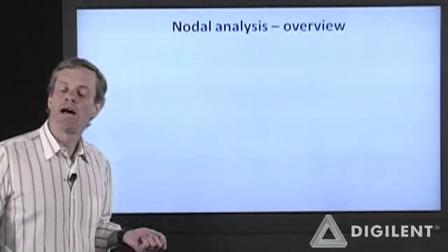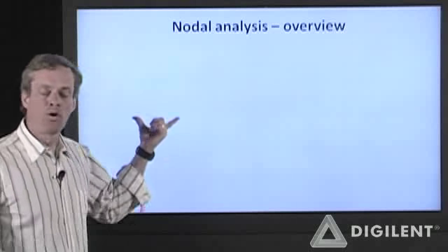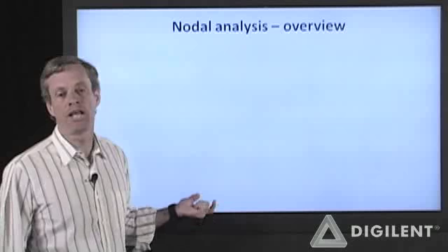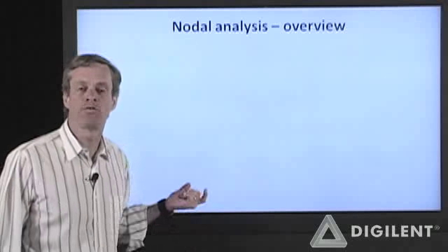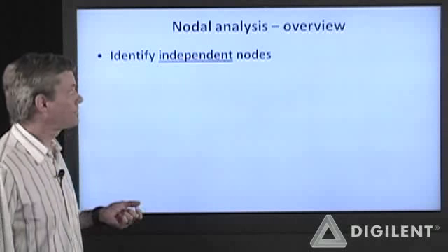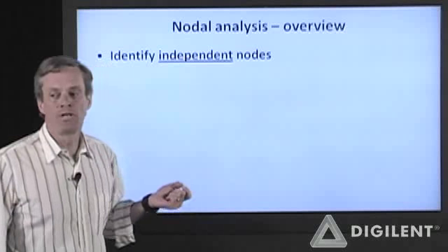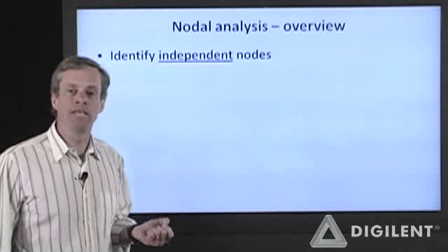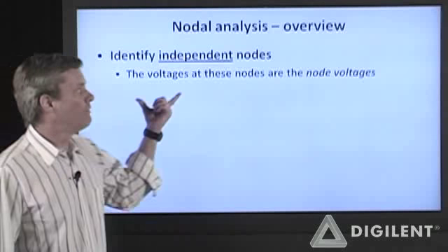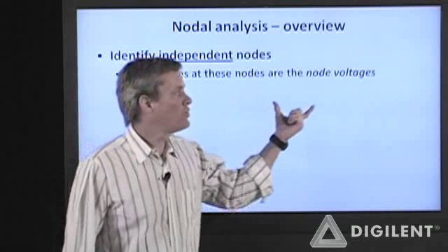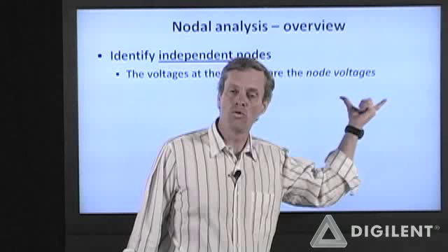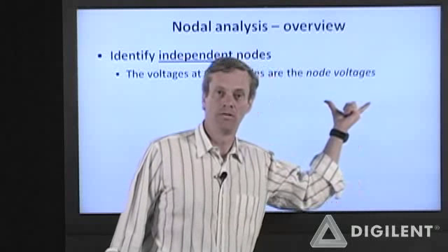Okay, next I'll provide a brief overview of the goals and the general approach for both nodal analysis and mesh analysis before we go into the details of how to apply nodal analysis. So our overview of nodal analysis. In nodal analysis, we're going to identify a number of independent nodes in the circuit. The voltages at those nodes will be called the node voltages. Those are our unknowns in the system.